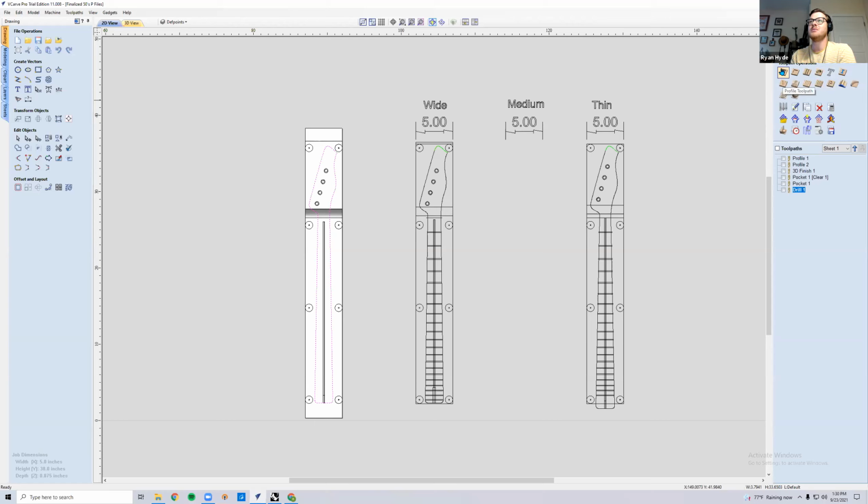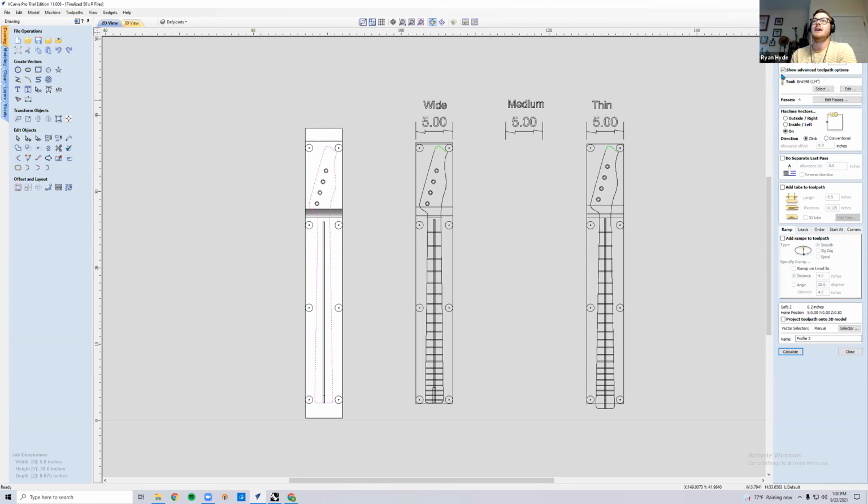So this one, and it's really tough to see with my big mouse pointer, is profile. If I want this to cut a profile toolpath, I'm going to go over here, and it's going to ask, what's your starting depth? Remember when I talked about the material surface, the material setup? That's set to 0.0 because I want it to start its cutting operation right at the top of the material surface.